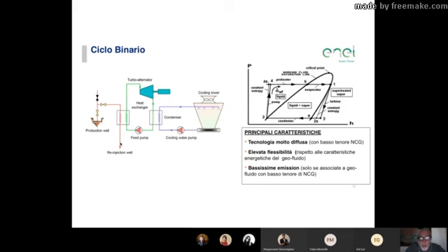As you bring the water up the well, because of the decrease in pressure, because within the well you have sort of a hydrostatic pressure column, the water will start to boil, and your non-condensable gases will go immediately into the vapor phase.